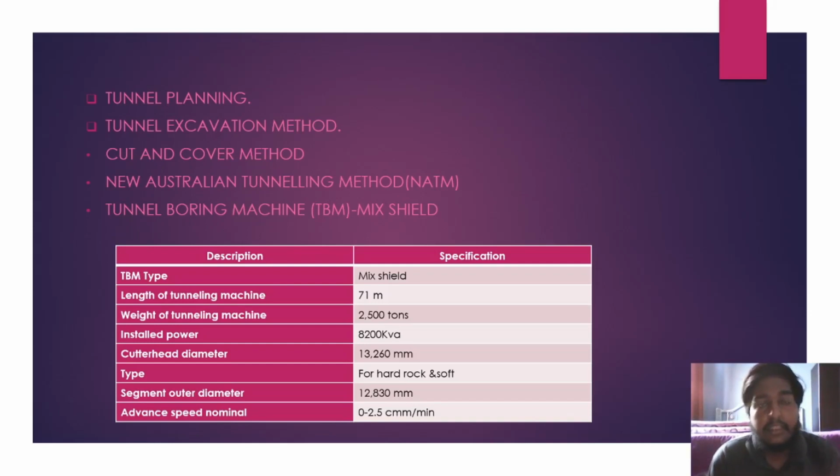Next, I will discuss tunnel excavation methods. First is cut and cover. As the name indicates, simply excavate, construct and backfill. There are some variations, for instance, it can be executed from the bottom up or top down. Both processes are quite slow during construction. A temporary roof over the pit is often necessary to allow surface activities to carry on unimpeded.